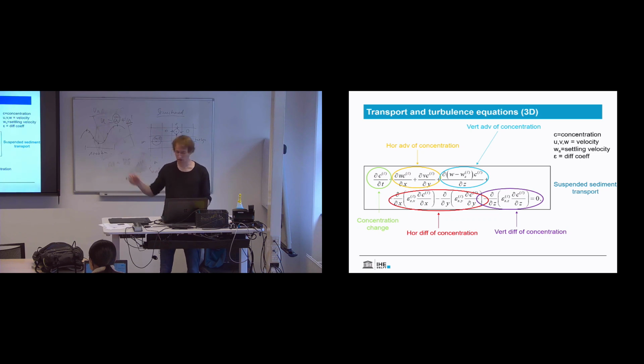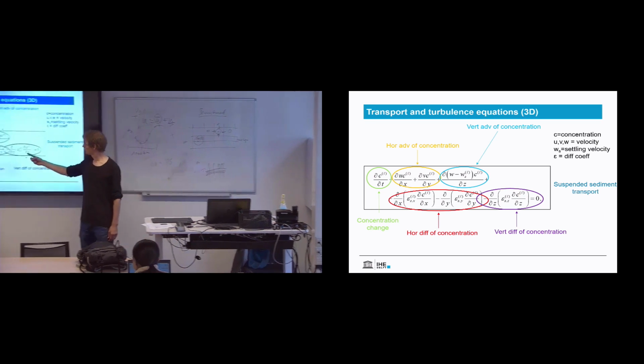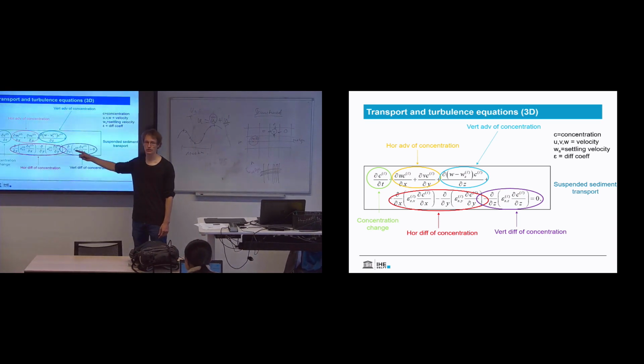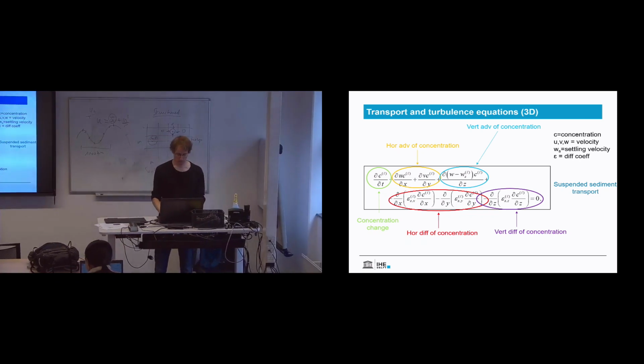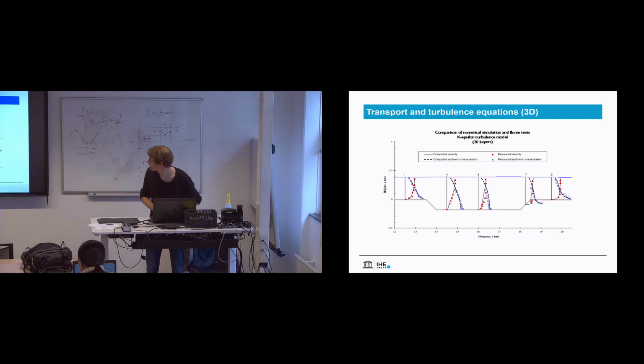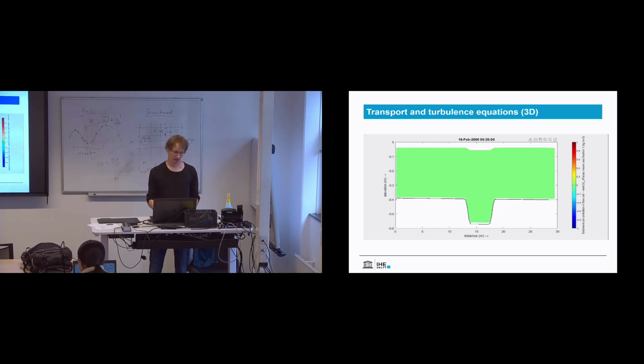Then you can calculate these vertical profiles, and most of the time this is taken as the flow vertical diffusivity, the same as the vertical viscosity of the flow. So you don't use something else here. And then you have seen this as a showcase of how good Delft3D is in modeling 3D sediment transport and flow curves. And I claim that FM is at least as good.